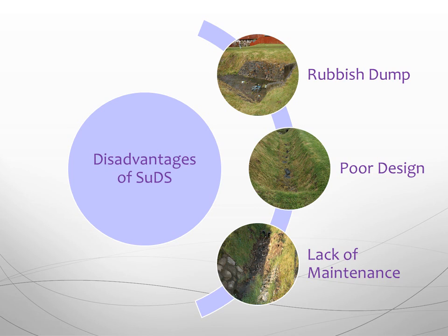A regular shaped deep ditch or pool with steep sides is unlikely to enhance the appearance of a development site or attract wildlife. Poorly located and badly designed SuDS devices will attract rubbish, again reducing the efficiency and amenity value. Old bicycle frames and shopping trolleys lining a detention basin or pond will detract from the amenity value.